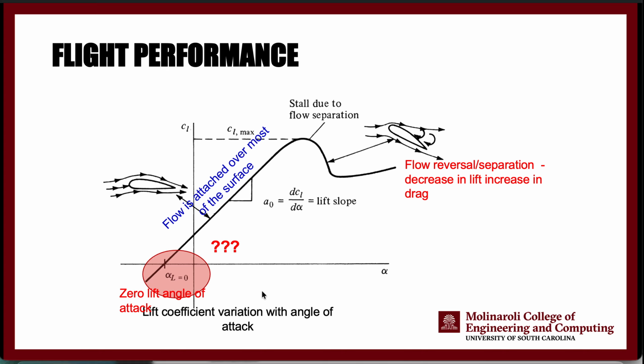So essentially the goal in the lab, and I'm going to explain this later as well, is for you to choose an aircraft, any aircraft, and fly it, record this data, CL versus alpha, drag coefficient versus alpha as well, and also the drag polar for your original aircraft.